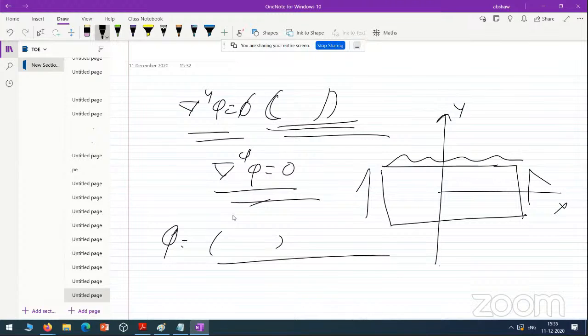You see, if this has to deform like this, then what will happen? The deformation of this beam is symmetric with respect to the y-axis. So the deformation at x is equal to the deformation at minus x. They both are the same. If they are the same, then the displacement equation should be an even function, right? If you substitute x or minus x, in both cases you should get the same value. Similarly, you need to look at whether there is symmetry in stress or not.